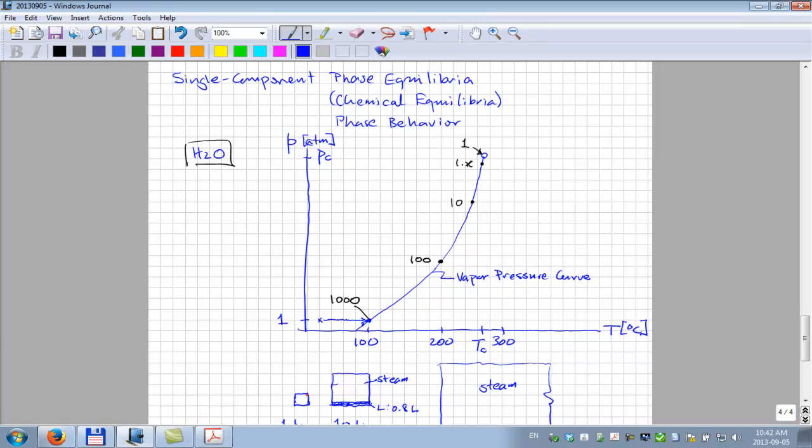Now what you can say, and a more proper semantic would be, this is gas-like. The air is gas-like. Well, that becomes a subjective definition. It's got a viscosity of around 0.01 centipoise. That's gas-like. A liquid viscosity is greater than 1 centipoise, what runs out of the faucet. The viscosity is not liquid-like, it's gas-like.